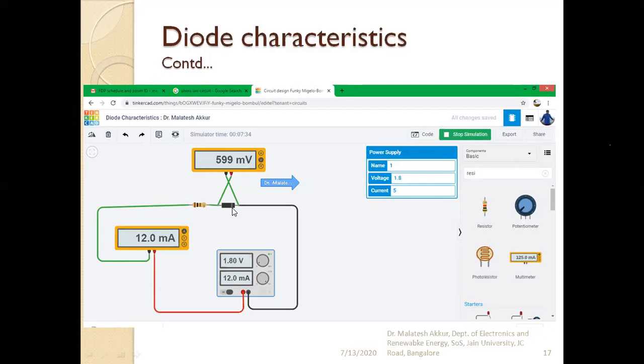But inside all of those there will be a rectifier, because we connect them directly to the AC power supply, and inside there will be a step down transformer. The 230 volts will be lowered depending on the device we use, like 12 volts, 9 volts, 6 volts, and so on. Once it is lowered, it is converted into DC using the rectifier, which uses the diode.